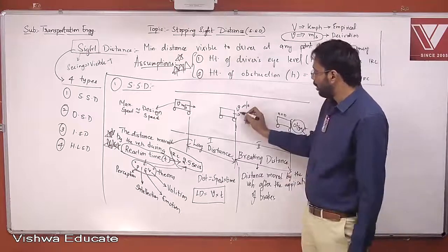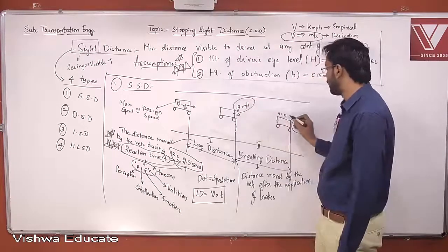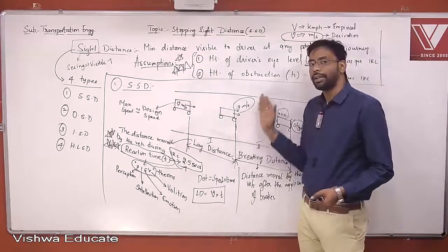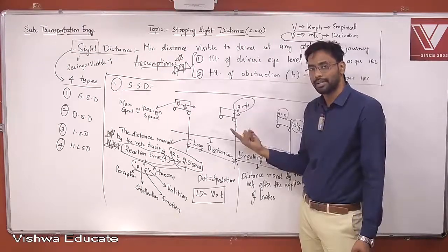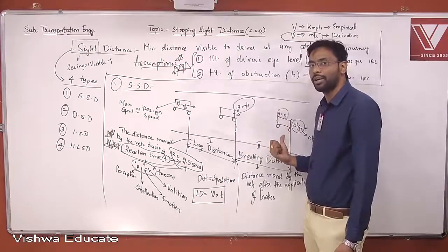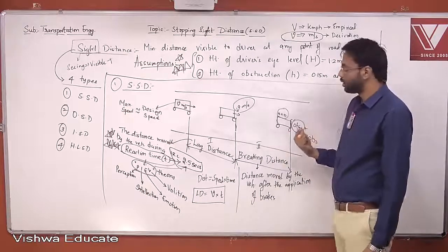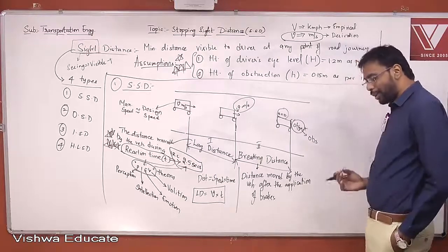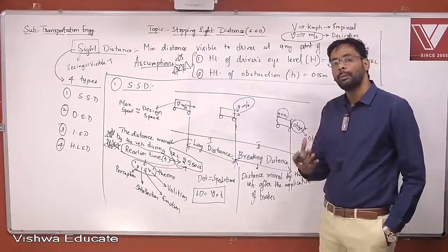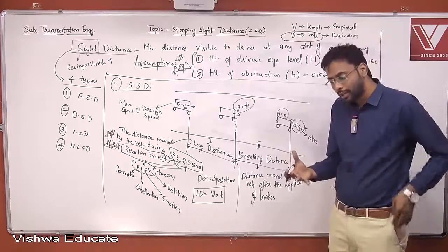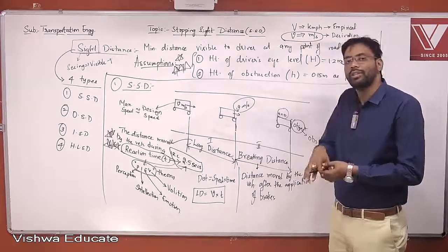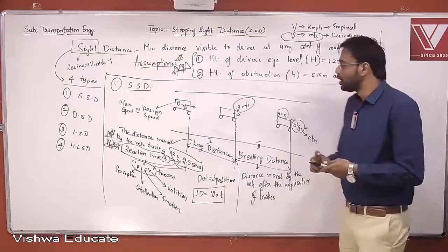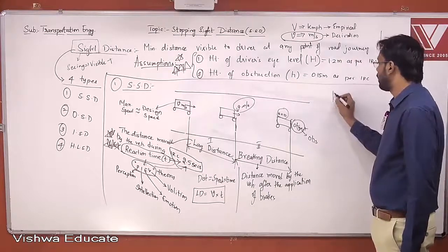Now this is important for us when we are solving some problems. So before applying brake, at that point velocity is the same as design speed, and after application of brake, at the end when it has stopped, obviously the final velocity is 0. Now what comes into picture when you apply a brake? Obviously, if you apply a brake, the force which is helping the vehicle to stop is frictional force, right? So let me consider this vehicle here.